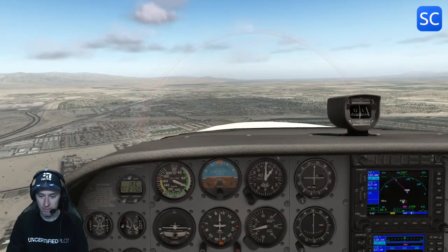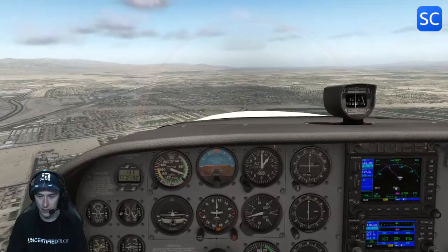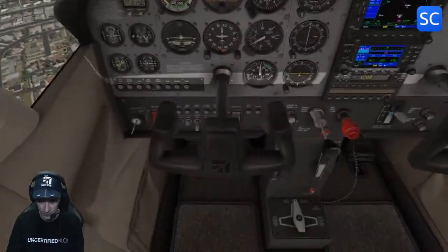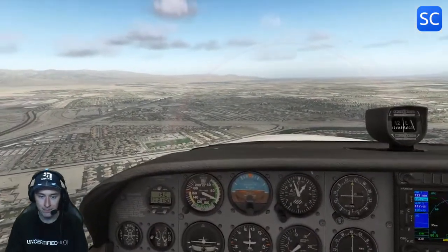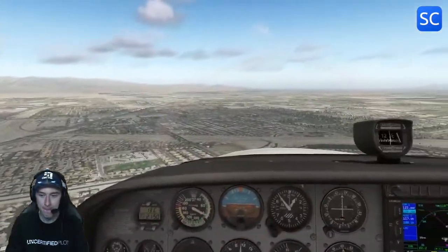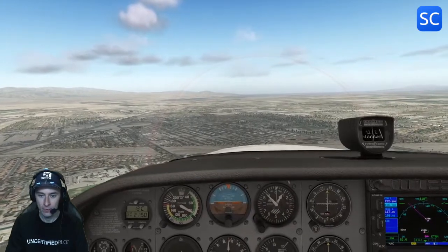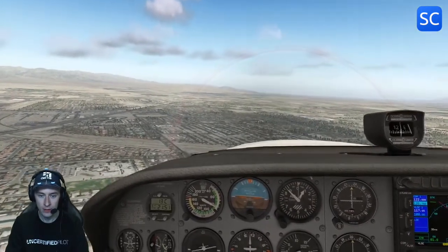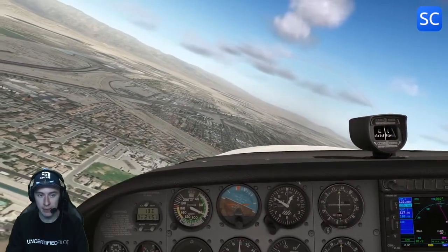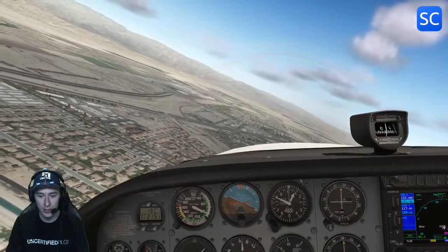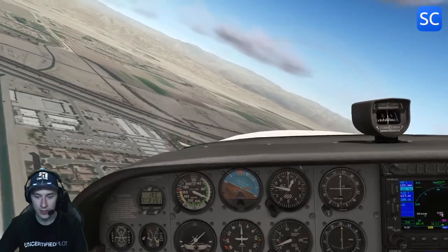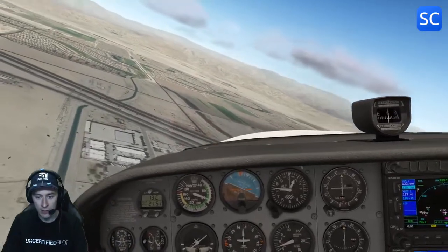Let's start descending, Tim. Alright, 1700 RPM. Again, landing lights are on, mixtures full in, parking brakes released, fuel tanks, fuel, yeah, that's good. Okay, I'm ready if you are. Alright, left pedals. Bermuda Dunes traffic, Skyhawk Hotel Tango Mike is turning left base to 28 full stop. Speed is in the white band, very important because I'd like to have 20 degrees of flap soon, and we can only do that while we are in that white band.